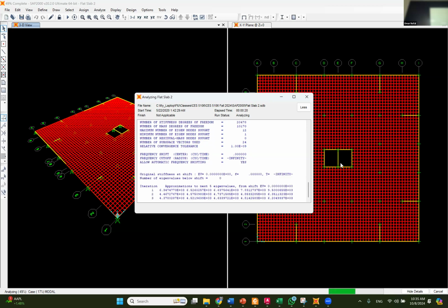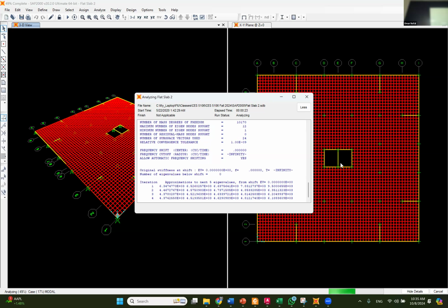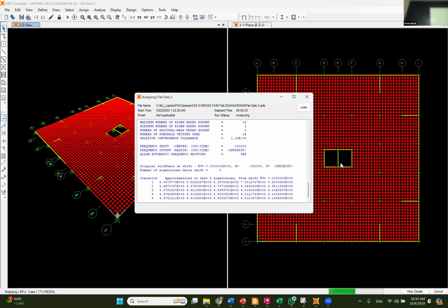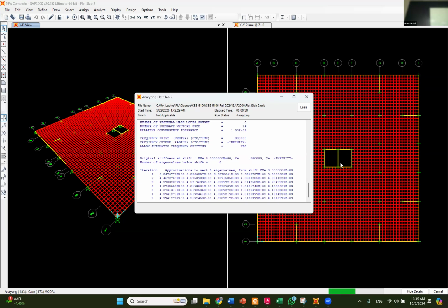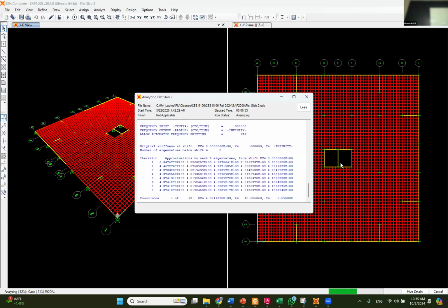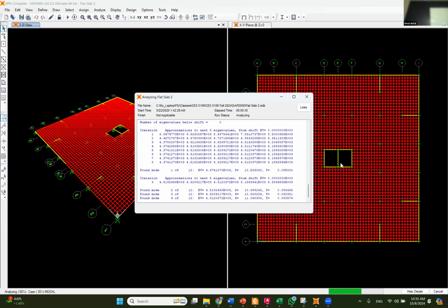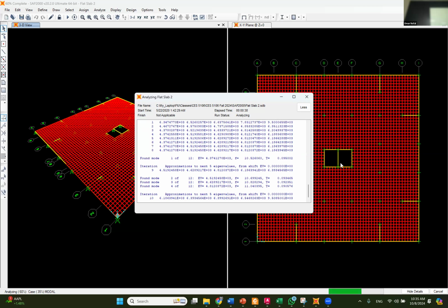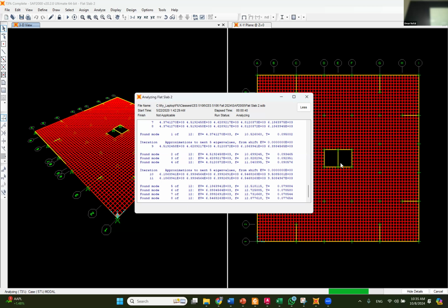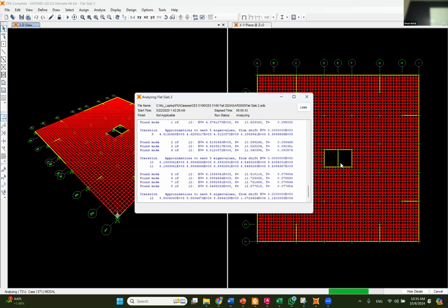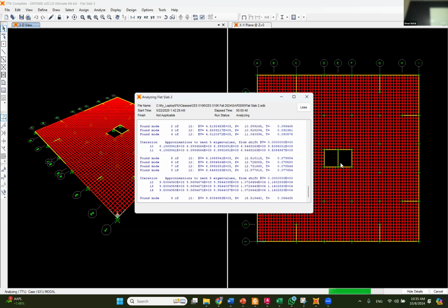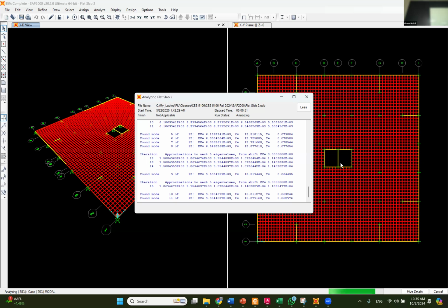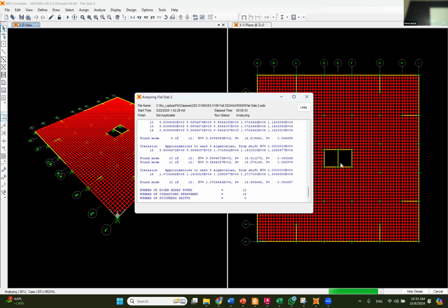Once the analysis is run, I go check the bending moment. There's a way that we can design based on the bending moment that we get from here and get the reinforcement for the slab system. But we are not doing design here. I'm just going to show you how to get the analysis result, how to get the bending moment on this entire slab. Once you get it, you can design it, find how much reinforcement, and do your structure analysis design procedures. And then you get the reactions of these columns, and design the columns outside, and also the reaction at the wall, and get preliminary dimensions for these walls so that we can do this 3D modeling.